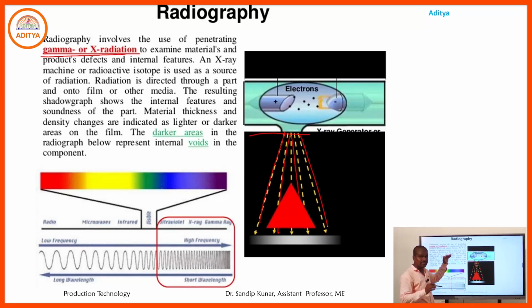As with the magnetic particle inspection method, when the radiation is deflected at the device, we can see that a problem has occurred in that particular area, and based on that we take care of the defects. This is also a non-destructive method, because we do not destroy the workpieces or weld joint plates, so we can reuse those pieces. That is the main basic point of the radiography method.